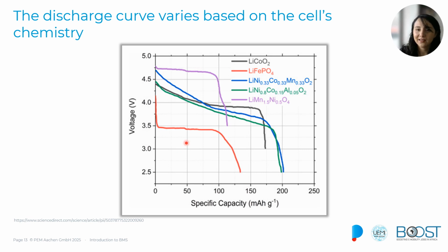But we can also see that the cells have this exponential range over here. As the battery is approaching the end of its capacity, meaning it is getting close to an empty state, the voltage drops exponentially. This sharp decline is basically signaling us that the battery is almost empty. And in the same way, in some of the curves, if we look close to the state where the battery is fully charged, it also has this exponential curve.